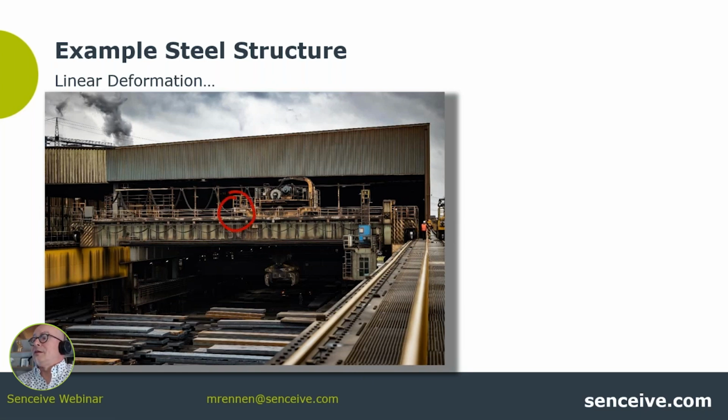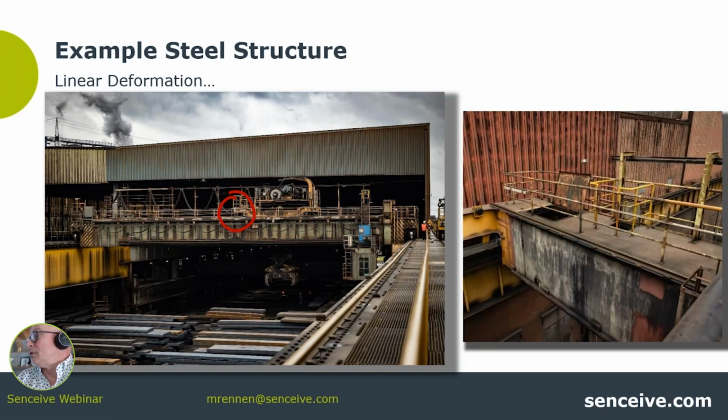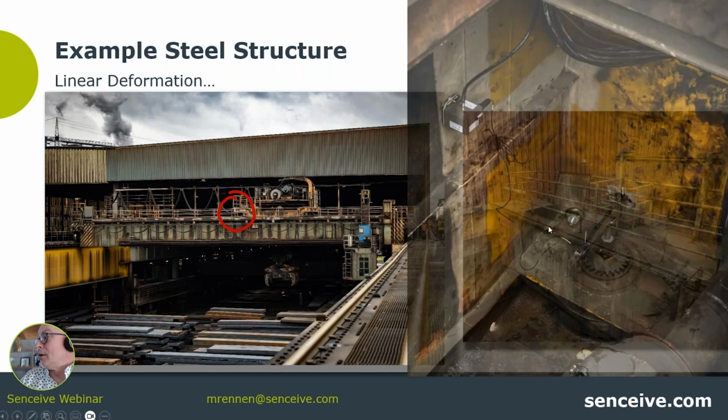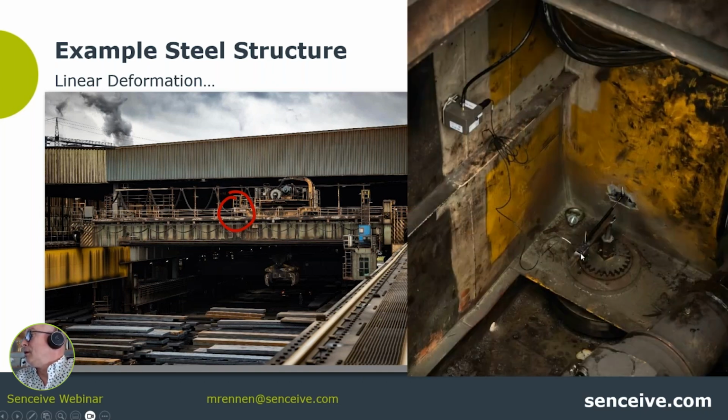And therefore, we had individual networks with gateways installed here on the cranes. Then we could sneak into these holes here and install crack sensors there as well to measure in all four corners the deformation of the crane itself. So not only the situation outside on the beams, but the crane itself.